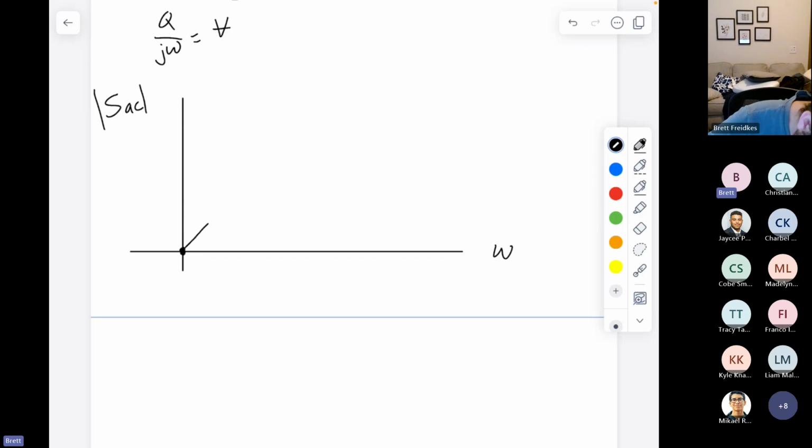And we see that that response ends up being approximately linear until we hit the bandwidth. That's the whole purpose, though, is to be inside the bandwidth. So before the bandwidth, which would be anywhere to the left of here, we're not at a constant sensitivity as it's constantly changing as a function of frequency. But after, we see that we are at a constant sensitivity in this flatter region within plus or minus 3 decibels.